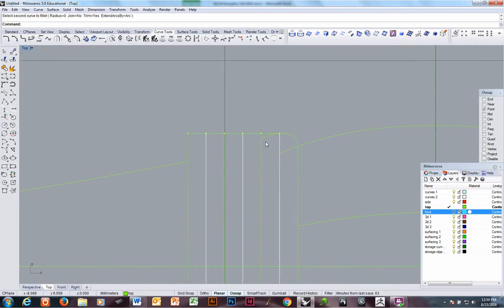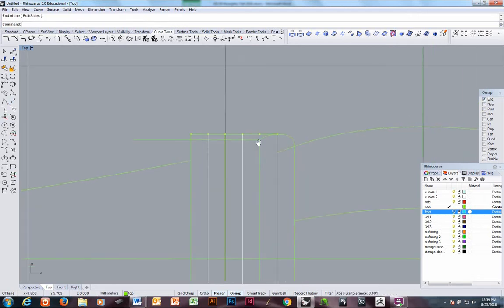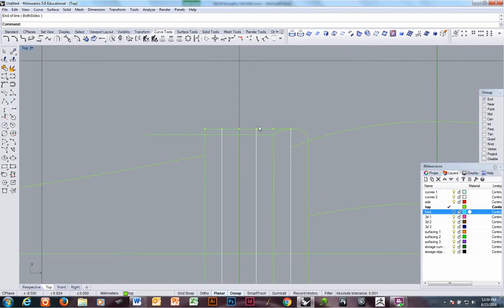Now for the next one, I want to do a regular arc. So I'm going to give me a reference curve, like in mechanical drafting, a construction line straight across, because I need a point here, here, and here to make my arc. So curves, arc tool, cascade arc. I want arc 3 points. So I have int, you do the top, beginning and end, and then you pick the middle.